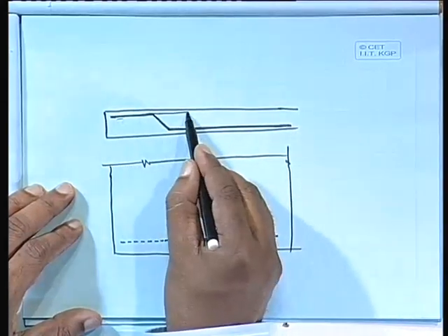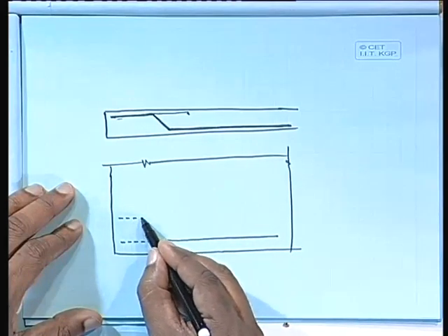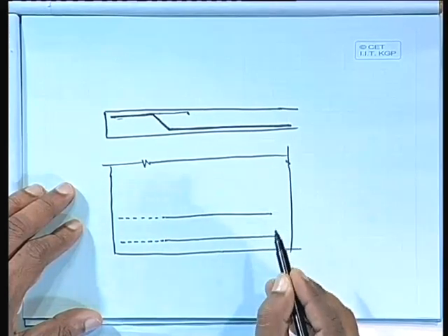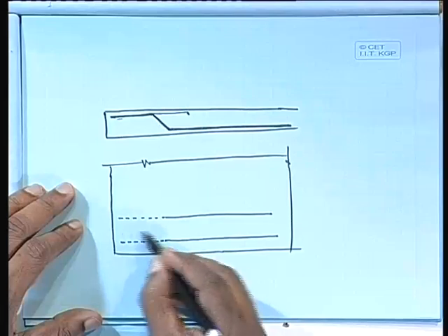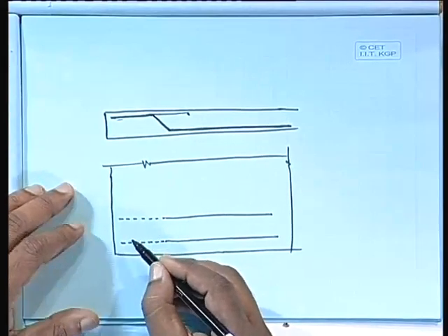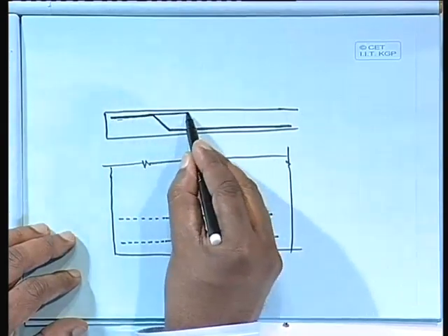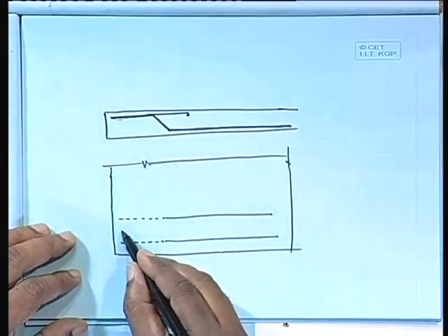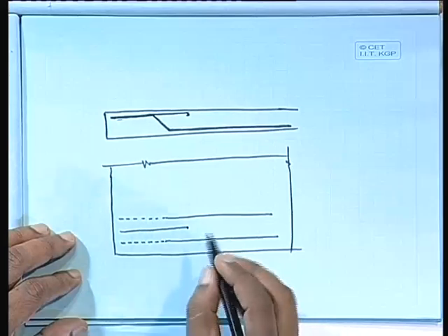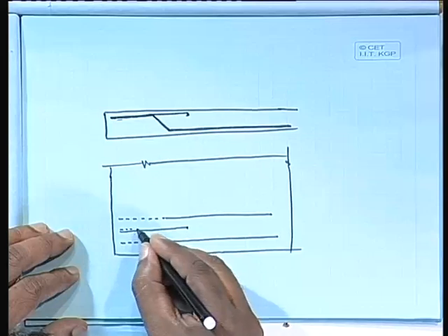The other one, because it may not be sufficient, what we can do is specify the other bar like this, it can go, and then again firm like that, but in between, let us say this spacing is not sufficient, we have to specify a little more bars. In that case, this is another bar, this is another bar, and we specify another bar like this. This cut piece we specify here like this, so that actually it should be, sorry, it should be dotted, please excuse me, it should be dotted.